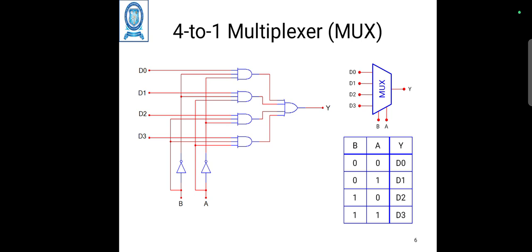So among the different types of multiplexers is the 4 to 1 multiplexer. We said here there are 4 input lines, and it will accept a single data selector. The 4 inputs are noted as D0, D1, D2, D3. And we have two select lines, let them be A and B. Here a NOT gate is connected and it is enabled. If D0 is selected, the output is D0, and the select lines should be 0 0. D1 is selected means 0 1, D2 is selected means 1 0, and D3 is selected means 1 1.